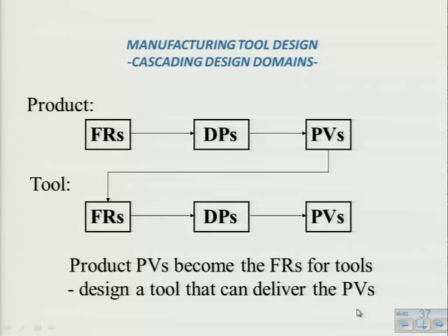Now, one of the interesting things when we do manufacturing is that we can come up with some sort of product. Let's take our shaft, for example. So it's providing a seal and providing a sliding interface. The DPs, we're looking at some sort of topography. To make those DPs, we might say, well, let's use a couple of grinding steps. Now, we're probably just going to go down to Saint-Gobain to buy some of the grinding wheels, or the grinding media, the grinding setup that we would need. Maybe we go to Supfina, buy a machine that's going to do this. And in many cases, everything we need is available commercially.